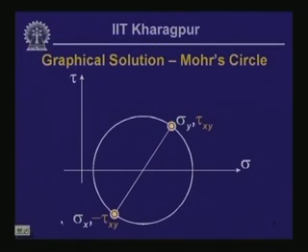Okay. So, actually we use a graphical construction in this case. You could do the same thing analytically, but what I am illustrating here is the graphical process, and the tool here is called the Mohr circle. So, we plot the states of stress on two orthogonal planes on a tau versus sigma plot. Tau is plotted on the vertical axis and sigma is plotted on the horizontal axis.